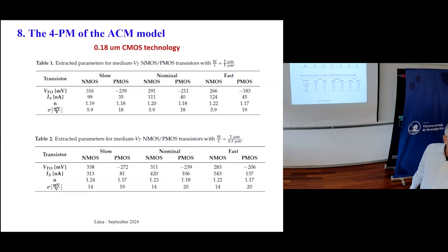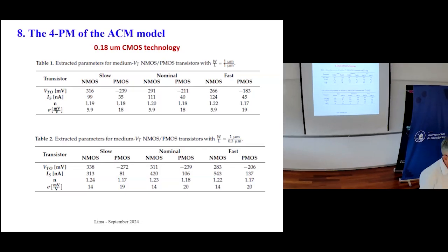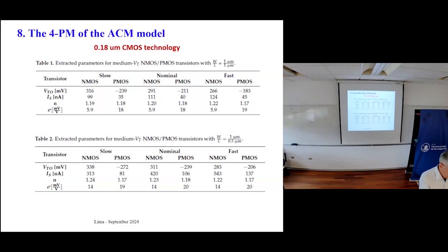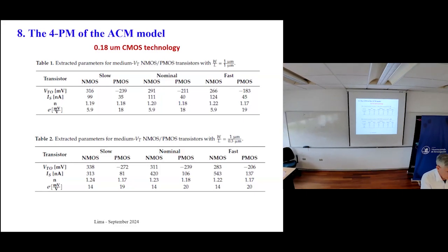Yes. There is a lot of rules. You have rules for printed circuit. You cannot say 2 metal lines. They cannot be very close. Otherwise, when you put some chemical inside to remove the copper, maybe there is some point here that the copper field makes like this and will touch the next line. So you have to ensure that the lines will not go together. There will not be a short circuit.